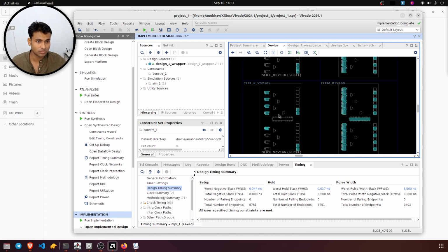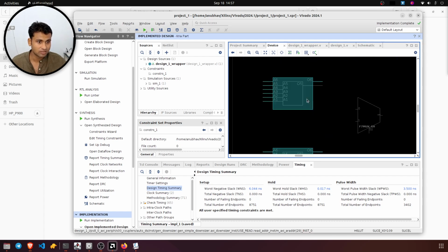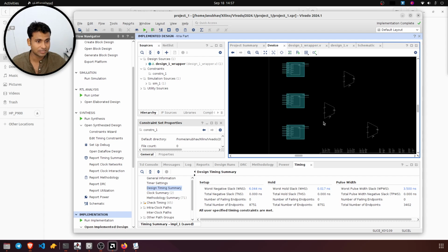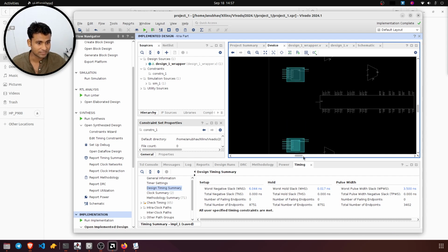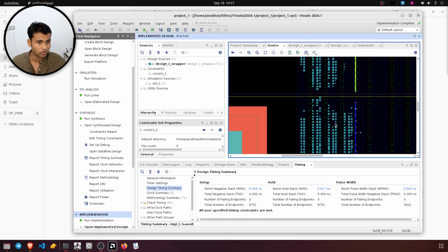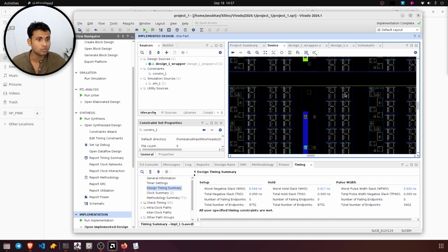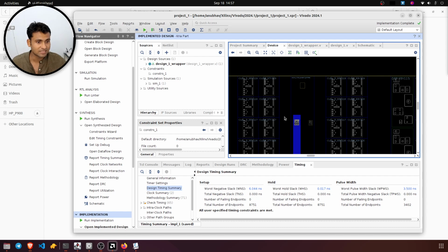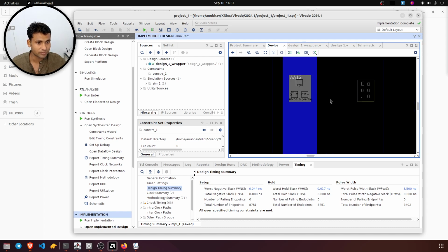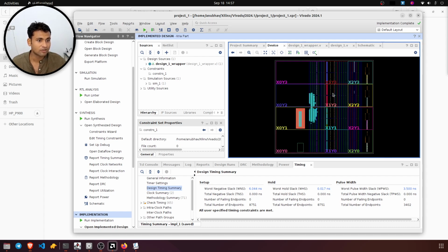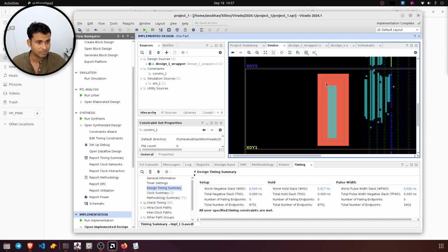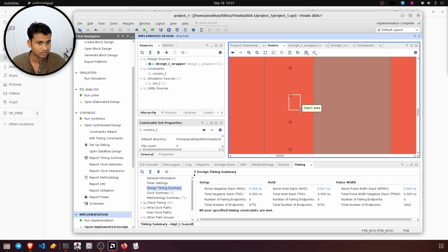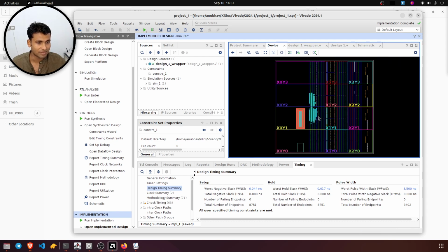You can keep scrolling, and in the most fundamental layer you will see the LUT implementation, the flip-flops, the BRAMs, and what all it is using, highlighted in blue. Even the DSP slices and the GPIO pins it is mapped to are indicated.